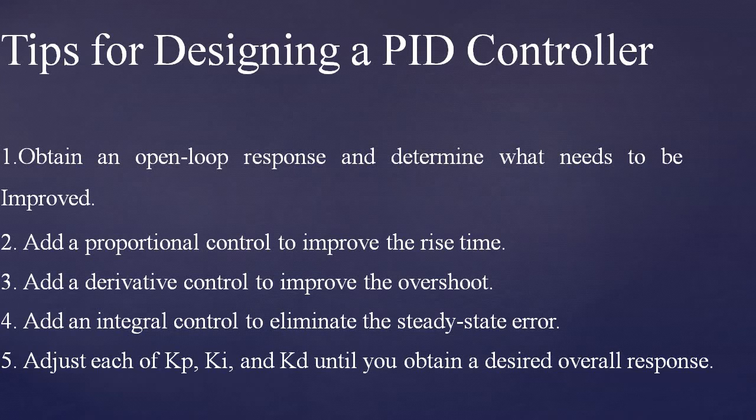And now, tips for designing a PID controller. Obtain an open loop response and determine what needs to be improved. Then add proportional control to improve the rise time. Next, add derivative control to improve the overshoot.